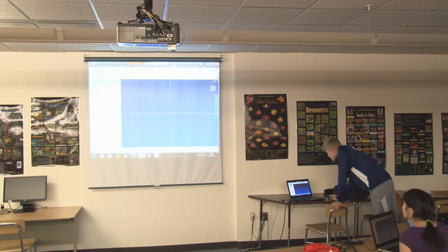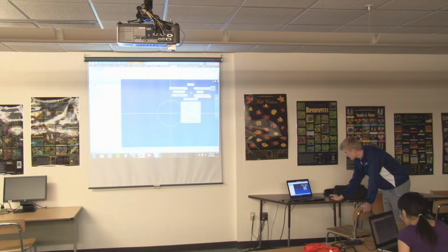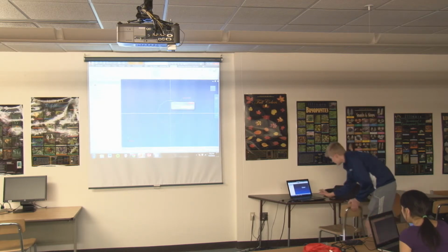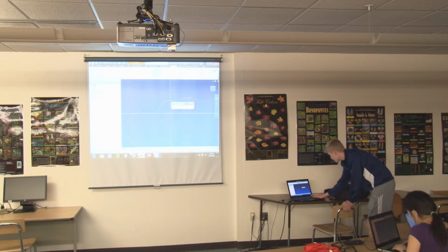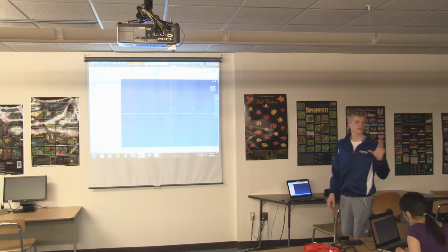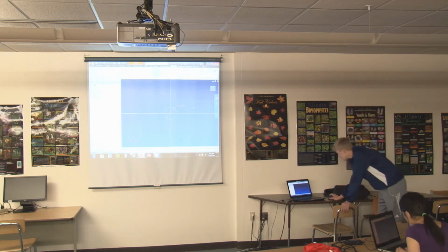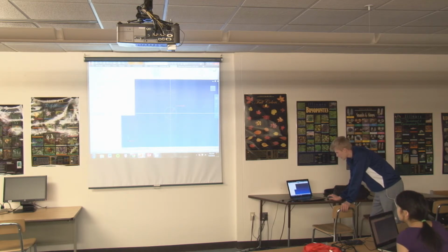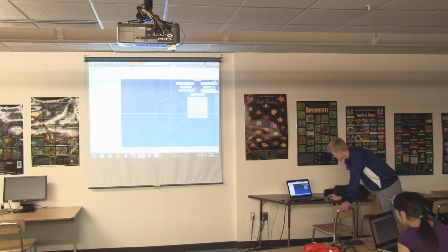So the first thing that you're going to do is create a circle, and you're going to create the inner diameter of that. So click there, and then right-click, General Dimension, and dimension your circle to 0.25 because we're going to be making a quarter-20 bolt. And then what you actually want to do to create the hexagon, the easiest method of doing it, is making another circle larger than the circle that you have. Say this one is 0.5.